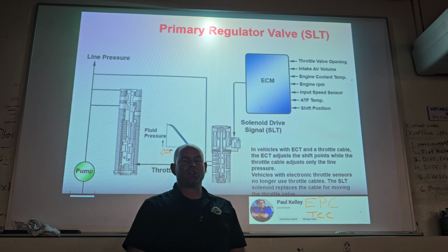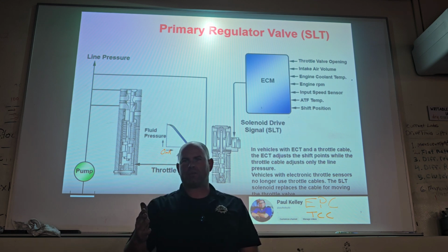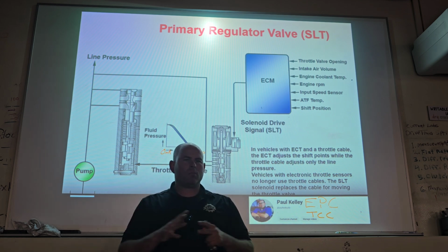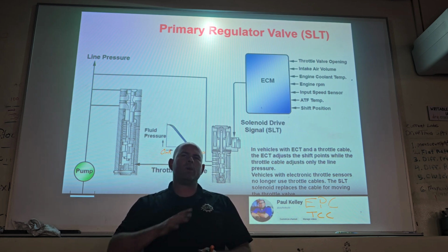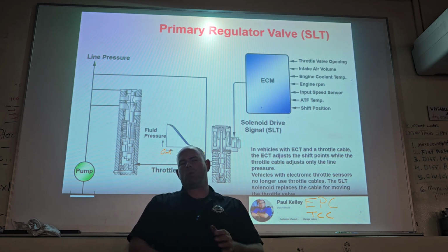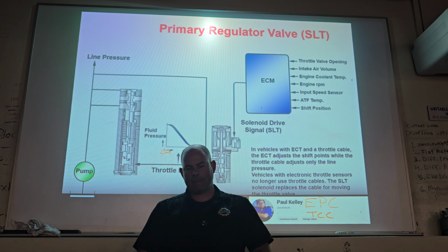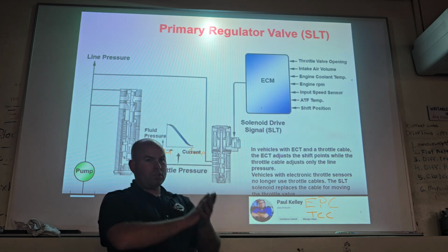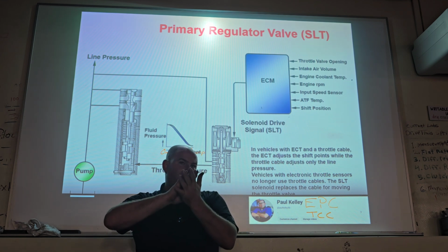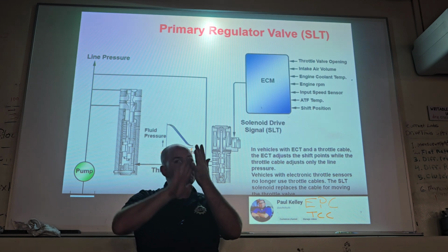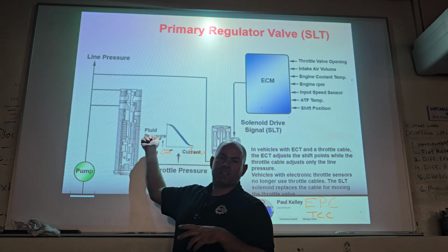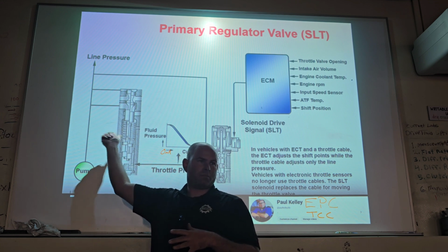All right, on purpose. Remember I showed you that Jeep when it lost power, it defaulted to third gear, right? If you disconnect the transmission, it loses power, or we blow a fuse, we want it to default to a fail-safe mode. Why do you think we want more line pressure than less line pressure? Remember I told you, clutches slipping wears the transmission out, right? So if I had low line pressure, don't you think the clutches would slip? Don't you think that'd burn up the transmission? Don't you think it'd be better to have this solenoid default to high pressure if it loses power?